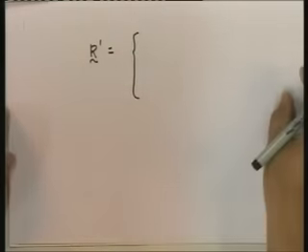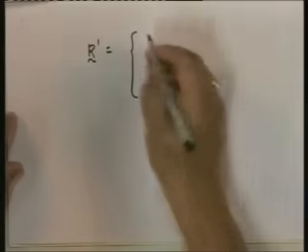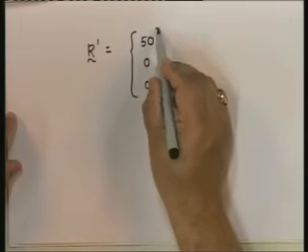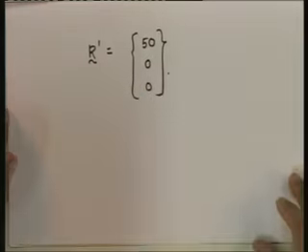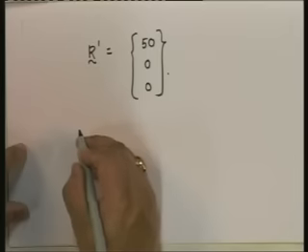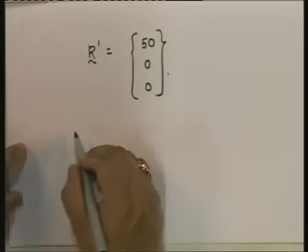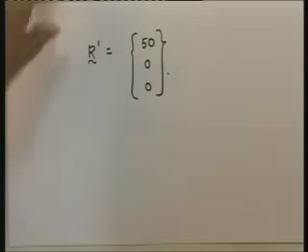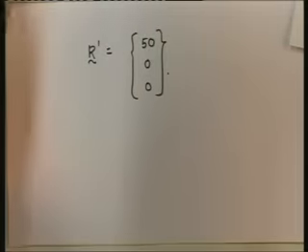Now, if we look at the R, and we find out the work done by the nodal forces, we will see that in this particular case this becomes 50 and these don't do any work. And so next we have to find out the Ai transpose into Ki Ai for each member. I'll first do it for the smaller members.